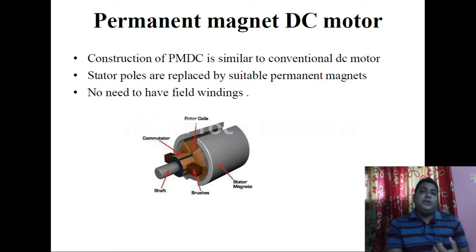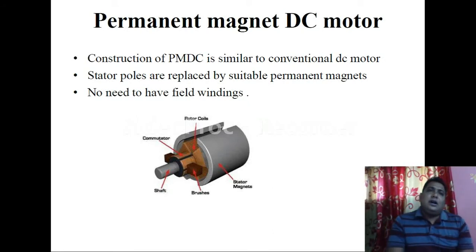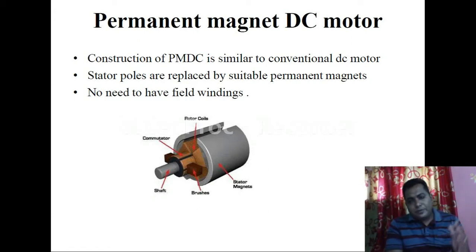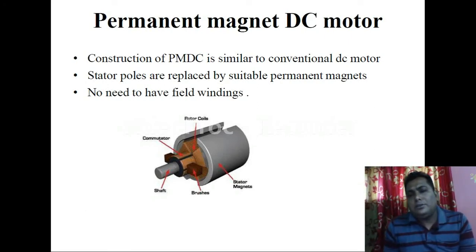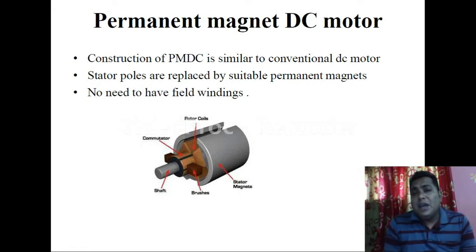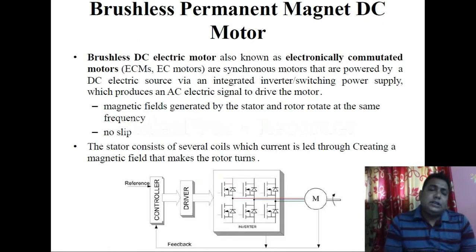The point is, if we think of a large machine, then we have to think of the industrial section. Whatever permanent magnets we would use would be large in size, and we know that a large permanent magnet has very high cost, and with long term use, the strength of its magnetic field reduces. Those are the different issues. That's why we are not using permanent magnets in those cases. For small machines, we actually use this permanent magnet.